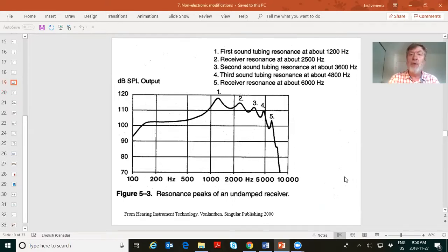And since most of the peaks in a frequency response, the biggest ones, tend to be in the mid to highs, that's where the effect of filters will be seen. So filters make the sound quality better for the listener, and they also reduce feedback, okay? Because they dampen the peaks in a frequency response. And what causes feedback? Mainly high frequency peaks in the frequency response.